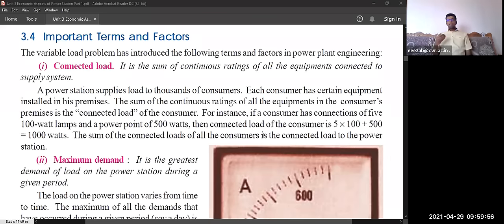So the load may be varying from time to time. You can't turn on all these appliances in all the hours; only in that particular time you can turn on and use those appliances. Washing machine means particularly it will work for half an hour or 1 hour. Then a refrigerator, 24 hours it is working. Like that, appliances may be changing. Iron box means 15 minutes to half an hour. Like that, it may be running. So next is this of connected load.